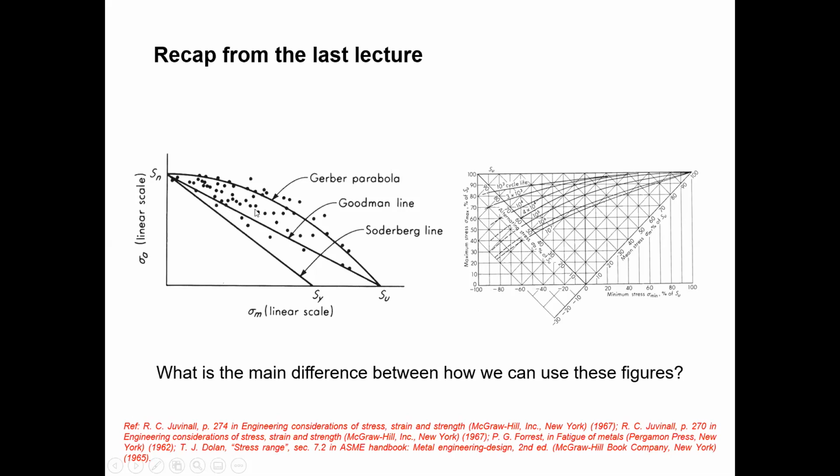So if it is above the Goodman line, but Tihan, as you just showed here, alternating and mean stresses. That's why you thought there are two stresses available, mean stress and alternating stress. But in here also both are available. The maximum stress comes from the mean stress plus the alternating stress. The minimum stress comes from sigma m minus sigma a. Are we clear, Tihan? So you can calculate the number of cycles.